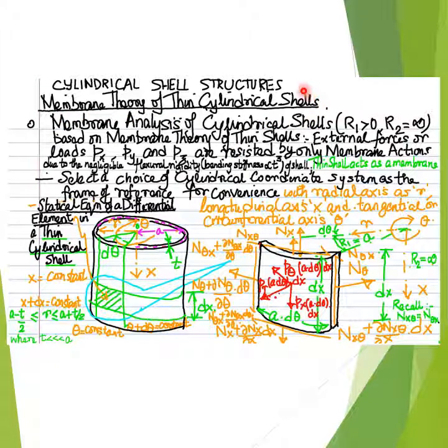In particular, a thin shell that qualifies the necessary and sufficient mathematical condition given by equation 1 presented in the previous slides for being a thin shell is unable to resist the out of plane bending moments and out of plane torsional moments, that is Mx, My, Tx and Ty, due to the negligible flexural rigidity or bending stiffness of the thin shell.